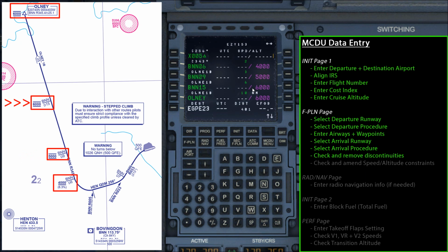And then you can see along the rest of the departure procedure, we have a couple more hard altitude restrictions of 6,000 feet. So what we want to do is compare the FMS data to that chart to make sure that everything is correct. To do that, if we go into the waypoints and then tap the right-hand button next to these constraints here, we can double check them.